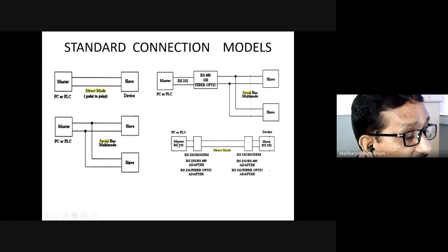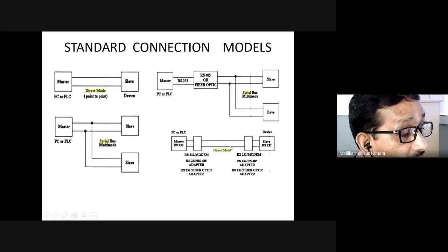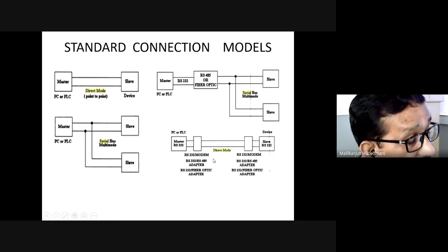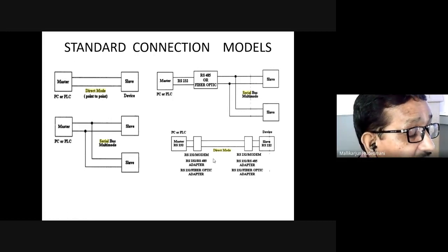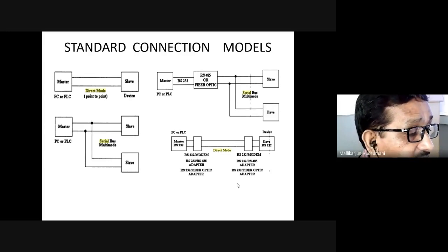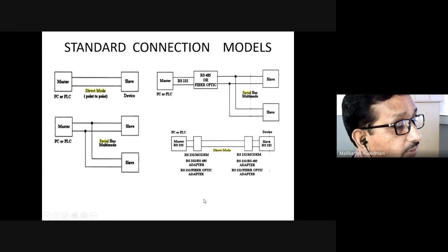So the master device, via the transducer, via the converter, routes the information via the service provisions to the end device, and the end device will return the information the same way. This way, a serial communication over a very large distance, or to far away places, we can connect. You can imagine this in a process industry or in a power system where the control center is really far away from the device, and you want to connect through that, get the information and take it in. This is how the communication mechanism falls into different categories.